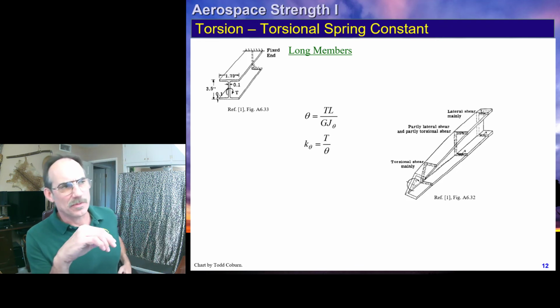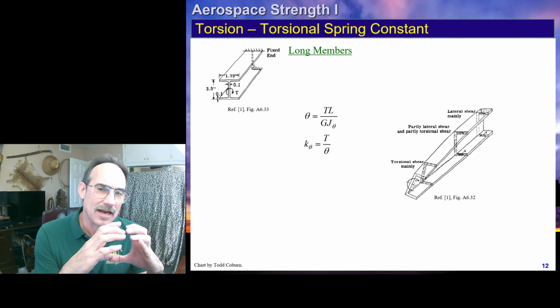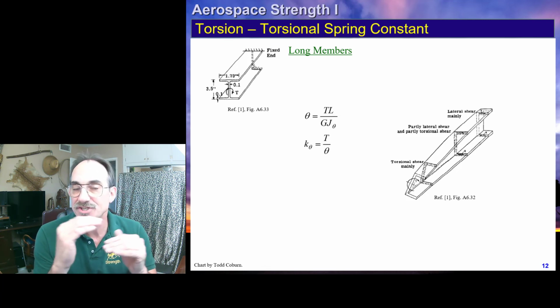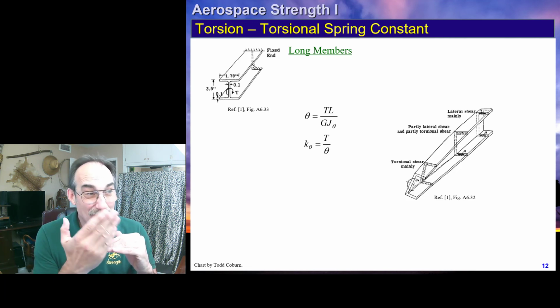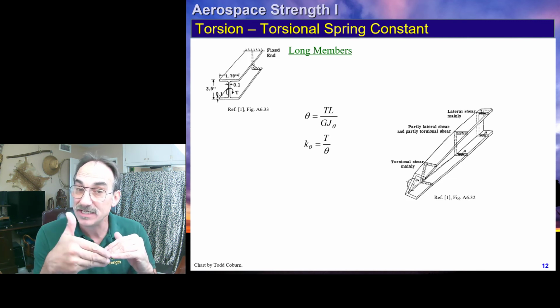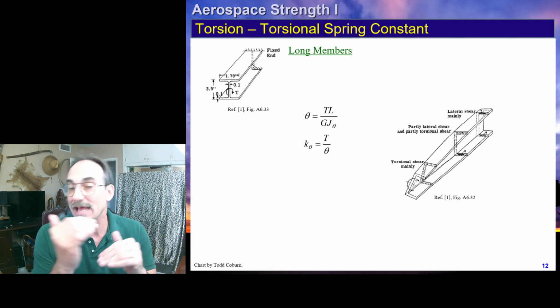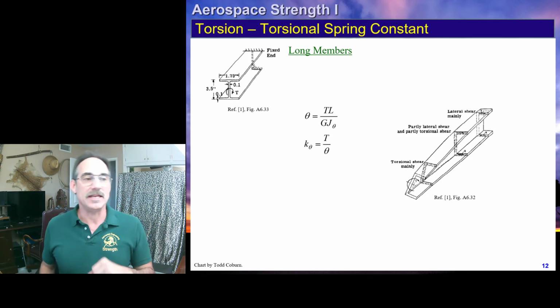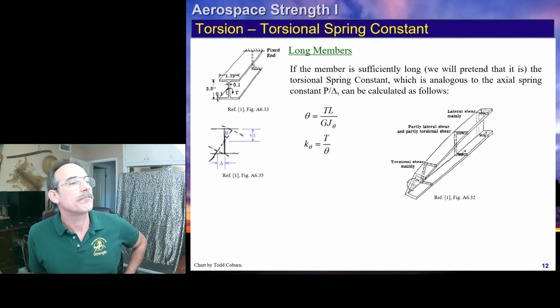There's actually another principle my older videos covered, and I'll probably move this to a different video and lecture in class. But there's also something called differential bending. What happens is the flanges of a beam are relatively stiff for bending, and so if you have torsion and it's got a really low torsional rigidity due to the flimsy nature of these things, you'll end up carrying that load. Part of it, if there's nowhere else for it to go, is differential bending between the flanges. We'll save that investigation for another video. That's what this is starting to talk about.